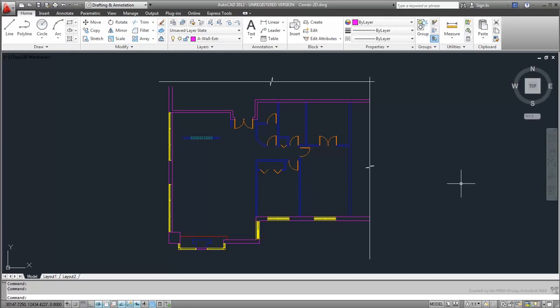You still can help a bit by creating polylines that 3ds Max can transform into 3D volumes. This isn't absolutely necessary, as you can use the 2D CAD drawing as it stands right now simply as a blueprint. 3ds Max has tools for building walls, doors, and windows, as is shown in another tutorial named Working with AEC Objects.